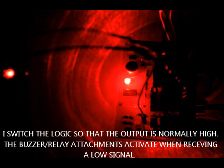Breaking the laser beam now. Notice the LED? So as long as I'm breaking that laser beam in the darkness, the LED turns on. So the output going to the LED, the output of the comparator, is normally low, which is what we want for our relay or buzzer attachments.